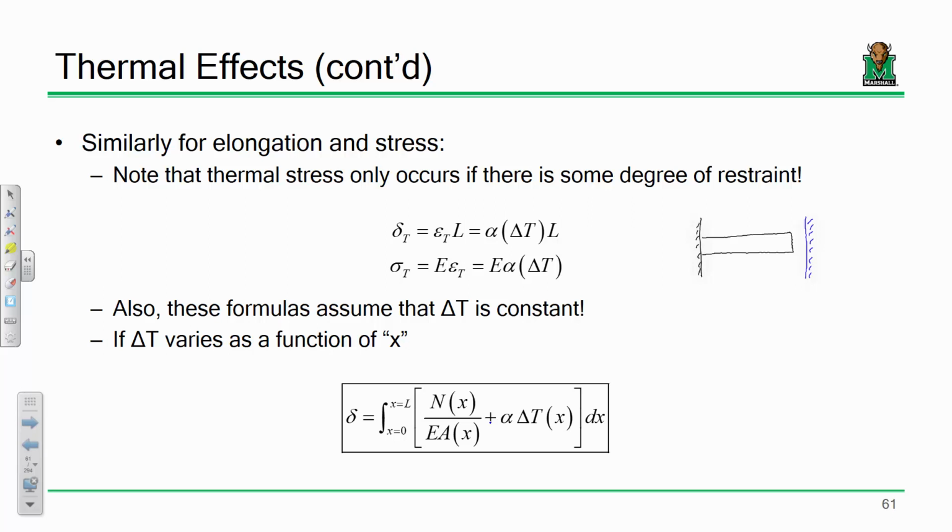So if I've got a bridge beam and I've got the two supports anchoring it to the ground, a fixed bearing is basically where you're taking the girder and you're attaching it to the ground. And we have a plate. There's some holes drilled in that plate. Well, for an expansion bearing, the holes aren't just circular holes. They're slotted holes. They look sort of like this, like there's a little oval shape to them. And the idea is that from summer to winter, as that girder tends to want to get longer and shorter, that expansion bearing allows the girder to move a little bit. So by allowing the girder to move, you're reducing that thermal stress.